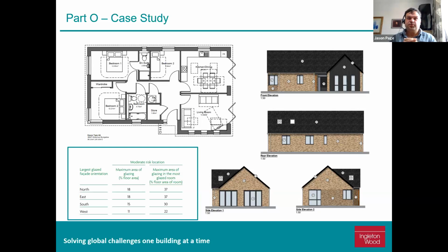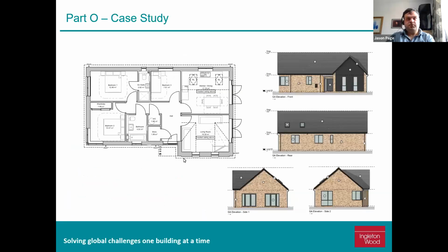This meant that we can use the window as fully openable for the daytime criteria, but use the tilt function at night to provide a greater opening than restrictors would, but give a greater opening area for the ventilation criteria for the nighttime situation, while maintaining a secure window. And this is the result. And whilst the glazing is significantly reduced, the building still has a good amount of glazing.